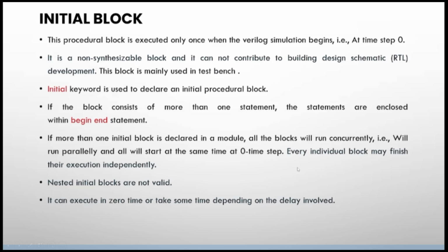Okay, now coming into initial block. In this initial block, as the name itself says, it will be executed only once. When the simulation is being done, when the code is being run, it will be executed only once. Whatever code that you are writing within the initial block will be executed only once.